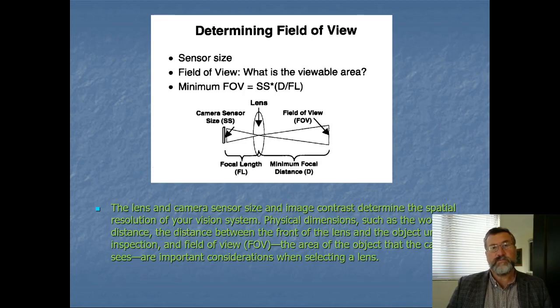Yeah, in other words, when we're trying to get a setup to image something in the field, we have to think about this because we want to think about the type of lens that we're going to use. And also, it's a bit of a black art, really, because that's why we work a lot with companies like Stemmer, because they've got a lot of experience in lens camera combinations. They know what works with what camera, what lens, and so they can give some good advice.